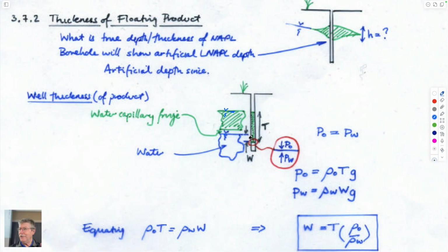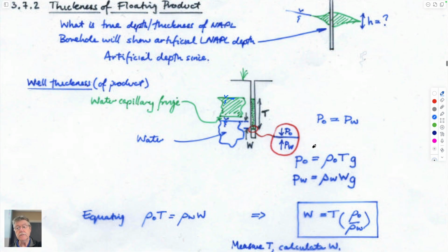And so you can again use marvelous fluid mechanics and statics to reconcile that by saying that within this borehole, the force acting down in the green fluid has to be the same as the force acting up in the water because they're in equilibrium. And we can define each of those. They have to be the same at that interface.